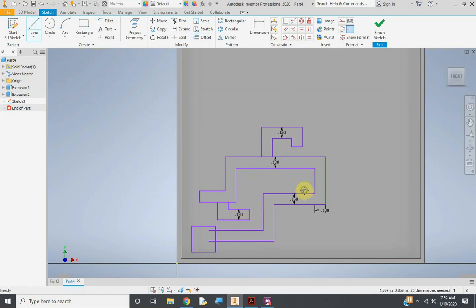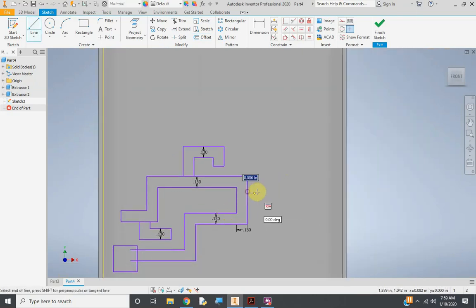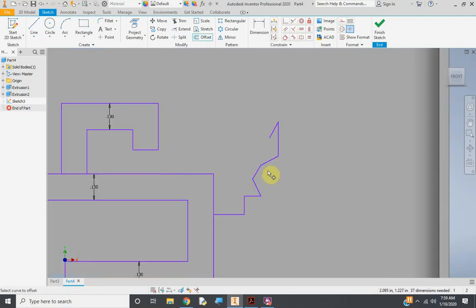So you might run into some errors. Do not do something like this where you have a lot of small turns like that. And maybe, like this is a good example right here. Okay, because watch what's going to happen when I offset it. The width needs to be 0.13. So I can't go any further on this one. Look how it stops me, okay? Or it messes it up. You can't do small turns. Make sure you keep your turns pretty wide.